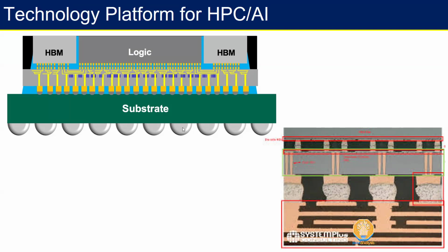Now, suppose you drop your mobile, right? And you drop your mobile, what happens? During that drop, it is going to experience a big shock, right? Because suddenly the gravity shock, because the mobile has dropped. Now, when the system inside that mobile, similar to this, experiences it, this solder can break, right? When this solder breaks, it would not work anymore. And that is the reason why you see in your mobile that your OS is not working, right? And then you take it to the technician, and he says, oh yeah, I have to do the soldering again. That means I have to remove this chip from the board, and then I have to do the solder again.